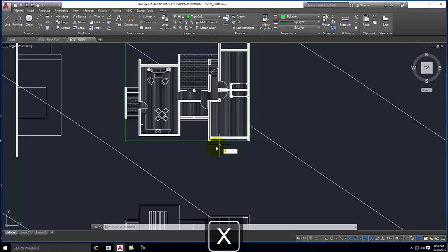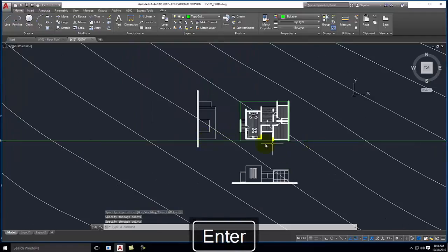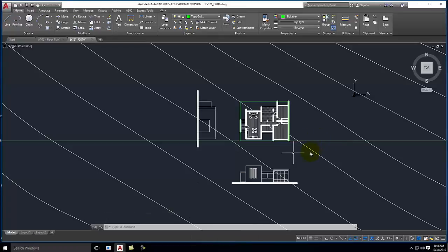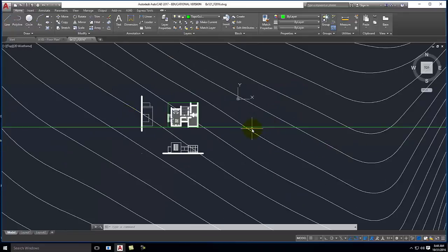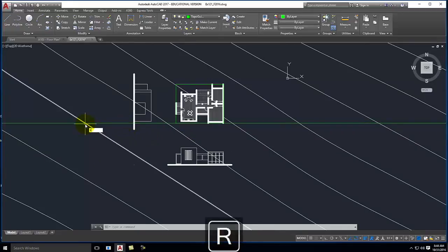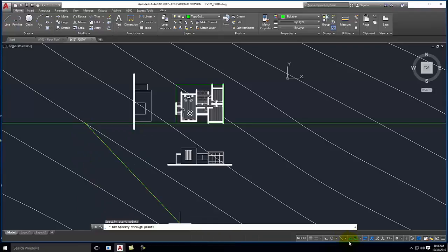I'm going to do a construction line, so an X line, right from the center, going off in both directions from right there. Okay? So like I said, the elevation is taken at that front face of the building along that bounding box line. Okay? And what I need to know is where this crosses the pieces of the topography around the building. And I want to extend out past the building a bit, and I'm going to draw a piece of topography that's much larger than my elevation. So if I look at that green line, I'm going to use the ray command to draw a line that goes from each point that this line crosses. So let's turn on ortho. So I'll have a point there.